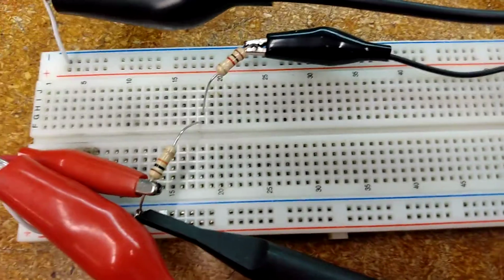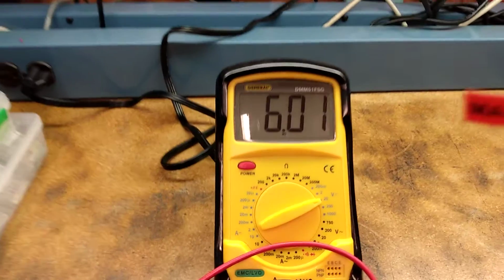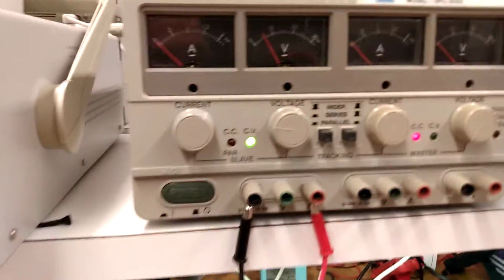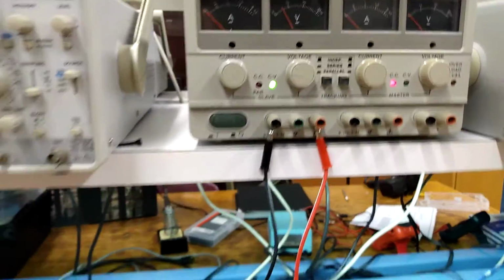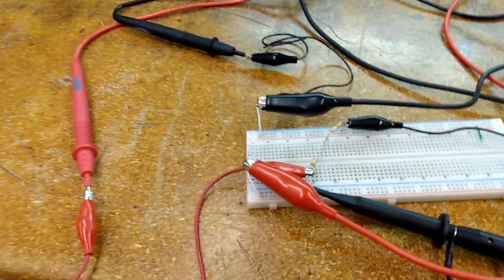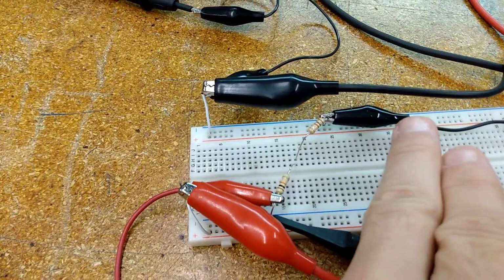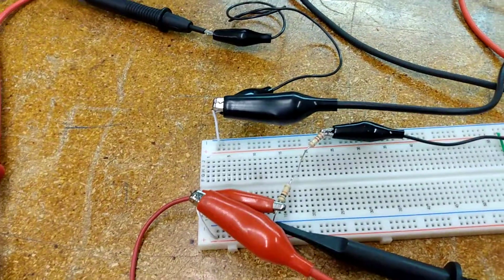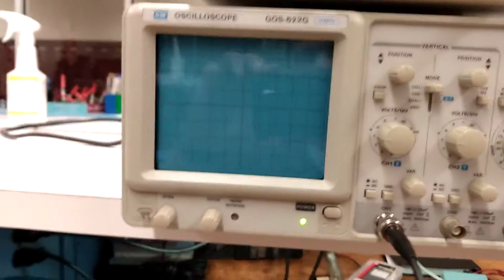In our DC section of the lab, we are asked to apply 6 volts DC, and that 6 volts is coming from our analog power supply right here, set at 6 volts. And the first thing we're tasked with doing is evaluating that on our oscilloscope. So we have our positive oscilloscope probe and the ground connection of our oscilloscope probe looking at the entire circuit, and we're going to look at our oscilloscope and see what we get.